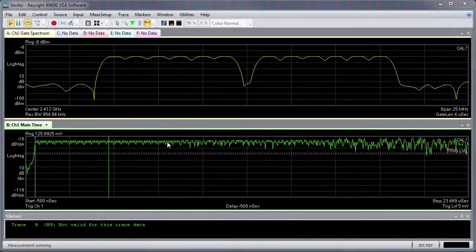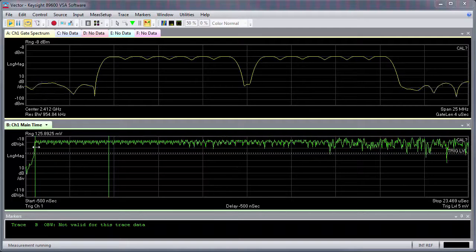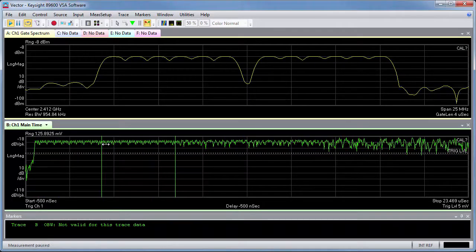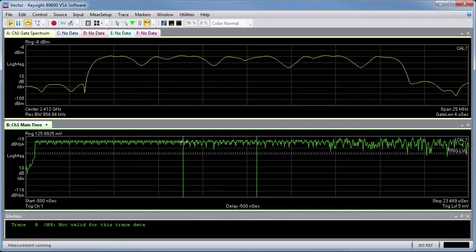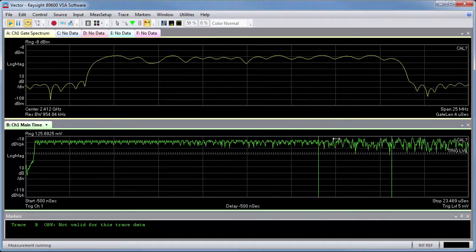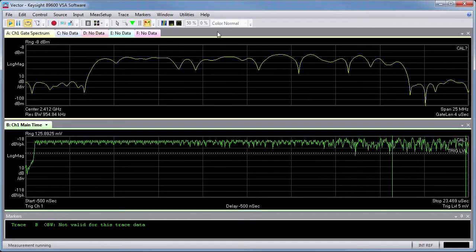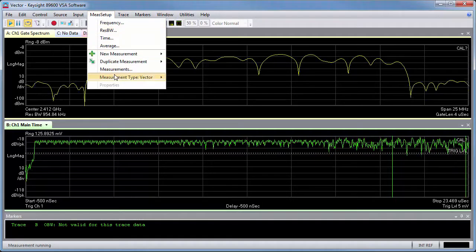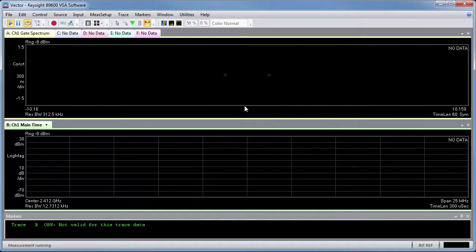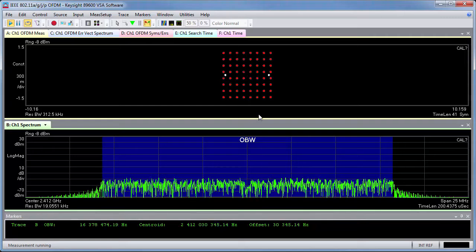Once the issue is fixed, we can look at it again. We now observe that the short training sequence is 8 microseconds as expected, and all of the other sequences also behave as expected in the time domain. Now, we can check if the signal can be demodulated. Everything looks great and behaves as expected. If this technique didn't lead to any discoveries, the next step would be to do advanced demodulation troubleshooting.